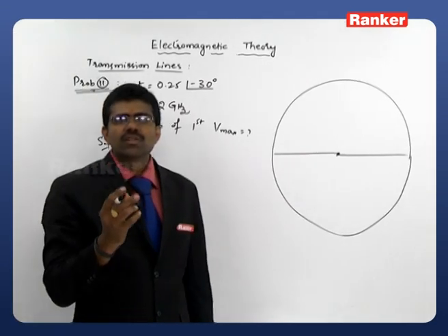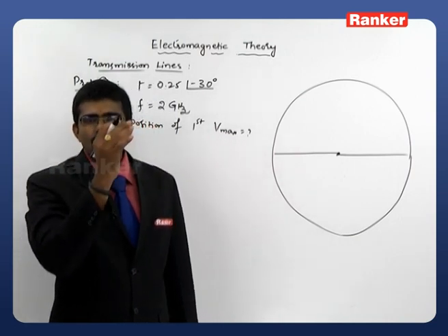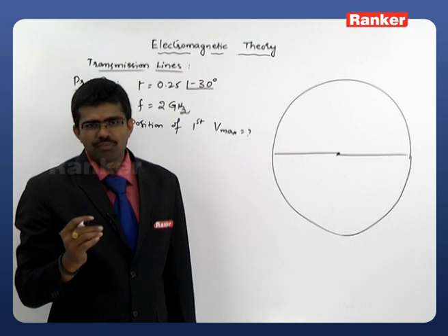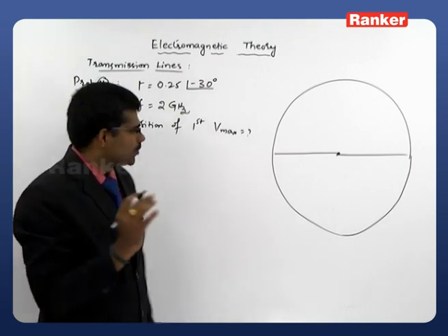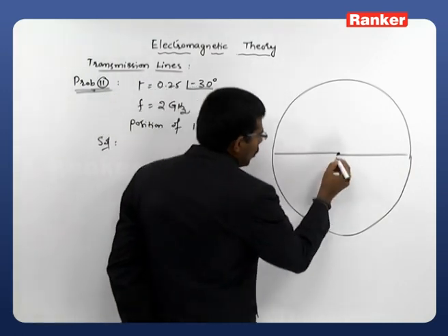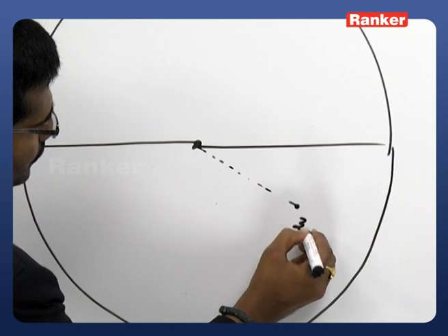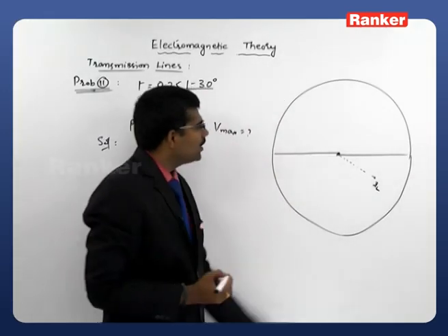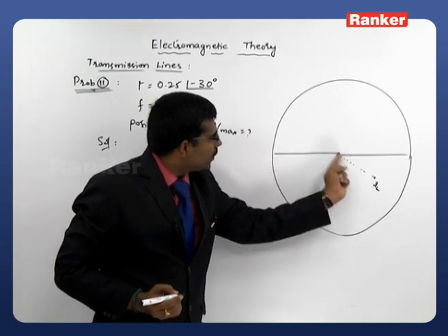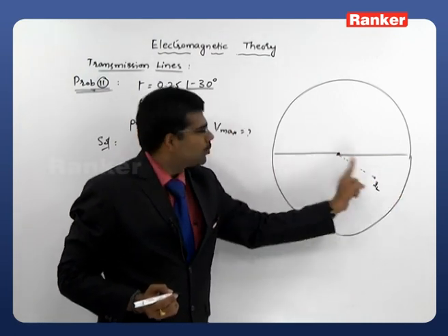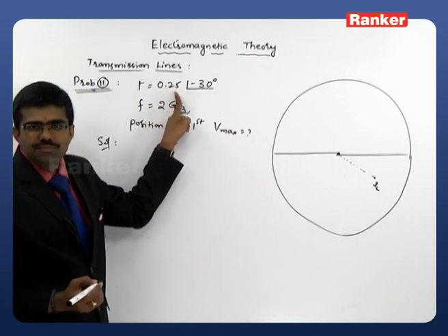The magnitude of the reflection coefficient is simply OP by OQ, right? The angle is POQ, or POS, or QOS, that is what we have. So just imagine how to observe this. Somewhere we have the load. As I know where the load is, I will take ZL here. The normalized load may be somewhere here. Now this is OP, and if you extend this line up to this point, that is OQ. OP by OQ will be equal to 0.25, right?